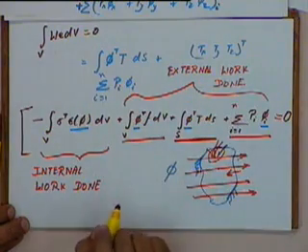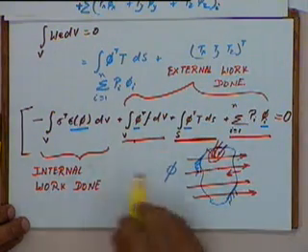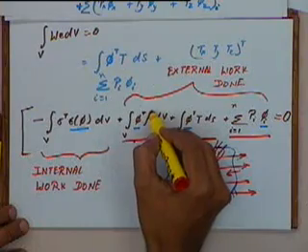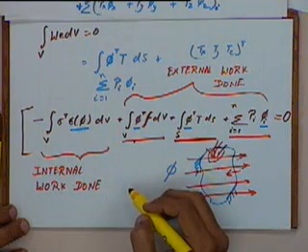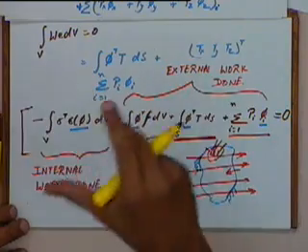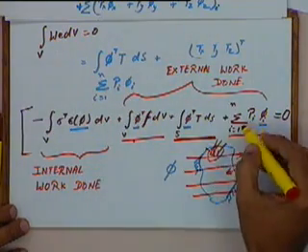What's the first term for these three terms? This one? Yeah. This is for the body forces. That means, let us say gravity, work done against gravity, okay, or there might be some magnetic forces acting on the body, which will again be on a per unit volume basis. Okay, so all those forces are the forces coming under this F, that is the body forces. This T is the tractive forces, that is forces acting on the surface, and these P's are the point loads acting on the body. Okay.